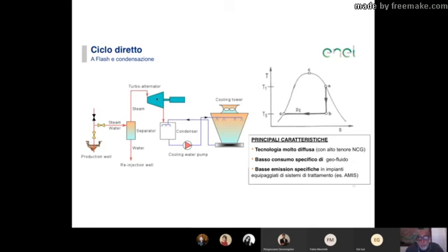So you can have a second turbine to produce more energy from the hot water that is at high pressure in the first separator, say at 20 bar, and then you drop the pressure to 5 bars so that the water can vaporize again, and you run this vapor through the turbine, condensing again at the end. So usually you have two turbines, two condensers, another separator, and you use the same cooling tower though. Yes.